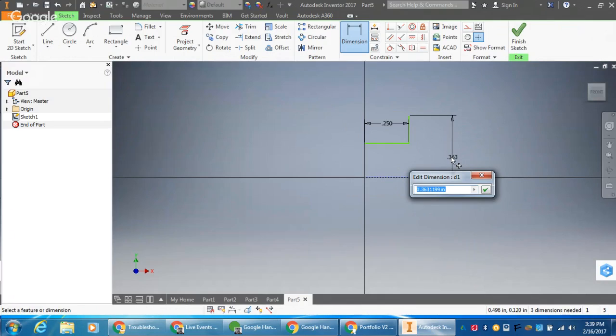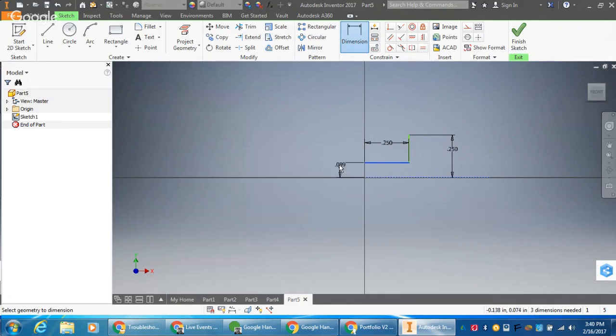You could take that measurement right off your drawing sheet, which is 0.25. And we have to be able to dimension from here to here, which is going to be the radius of that hole. If we take a look at the radius of the inside hole, it's 0.28. So 0.28 divided by 2, because it's going to be a radius because we're going to revolve.